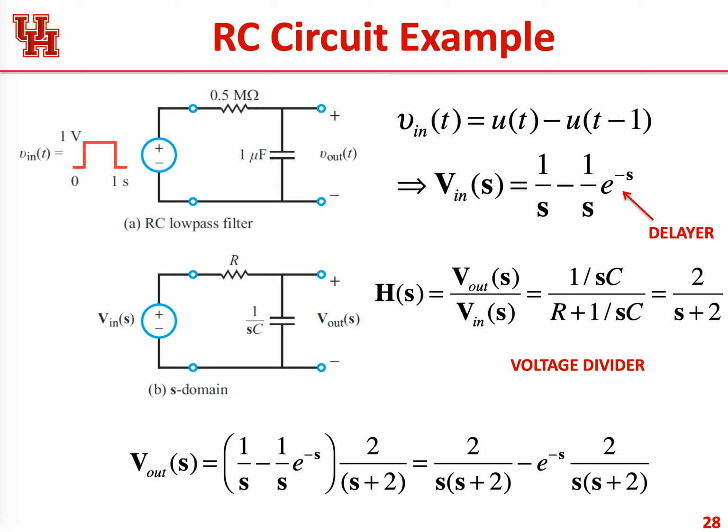And so we got the RC circuit like that. So I can directly go at it in the Laplace domain. So I'm going to write this as 1 over SC, right? And my Vin was a pulse, right? So this was a pulse that started off at 1, so it was like u of t minus u of t minus 1, right?